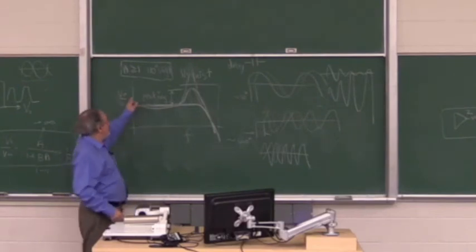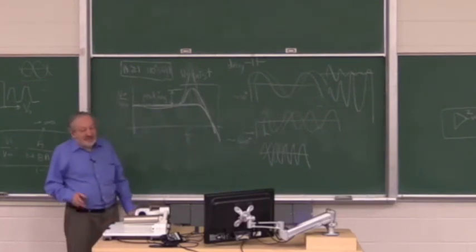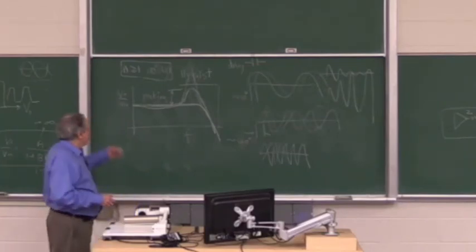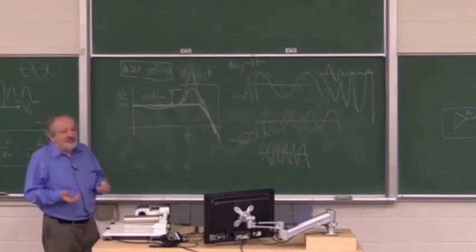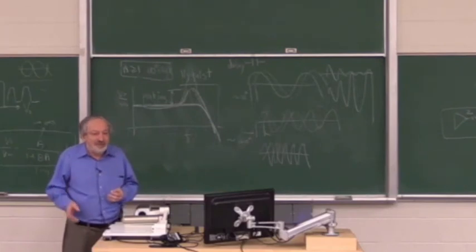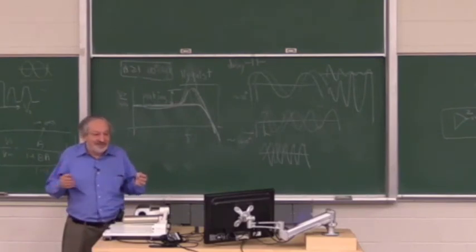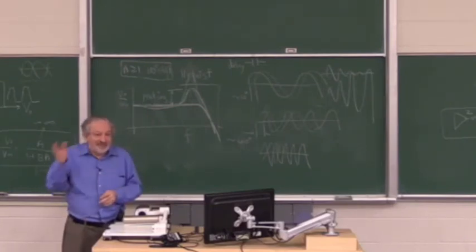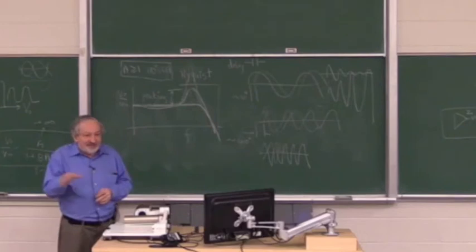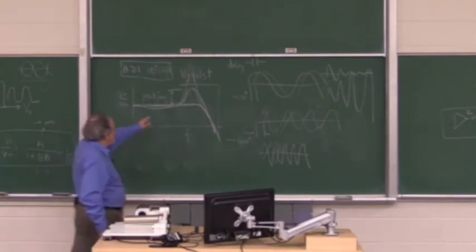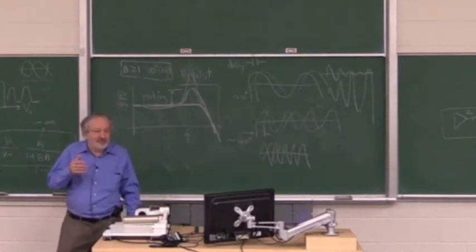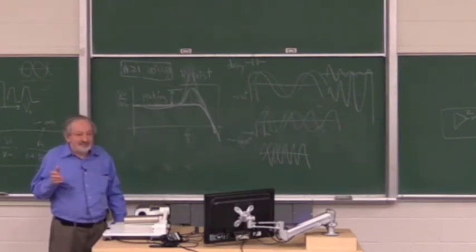Typically you see these graphs relating to simple op-amps, right? But this concept is true for any feedback system in the world. Could be hydraulic, could be very complicated, even a complex modern system with predictors and machine learning and everything. If you run it faster and faster, and you see this, you know that it may be unstable and you worry about it. Where does the delay come from?